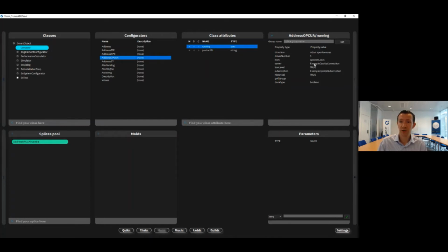This is a valid configuration, but the OPC item name in the server is not always going to be the same. If we create multiple conveyors, we're going to want to read slightly different items from the OPC server based on the naming convention that the OPC server is using. So to do that, we can use these parameters. So if I put a parameter saying Opc Ua conveyor name, this is the conveyor name as represented in the namespace of the Opc Ua server.